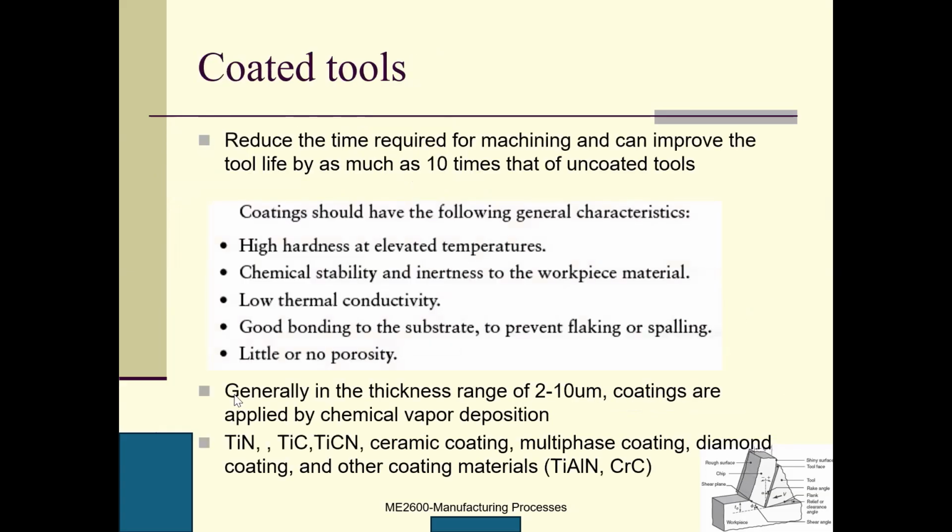Coated tools. As the name suggests, we have the tool insert, but for some reason, we want to coat this tool insert using some coating material. This coated tool reduces the time required for machining and can improve the tool life by as much as 10 times that of the uncoated tool.